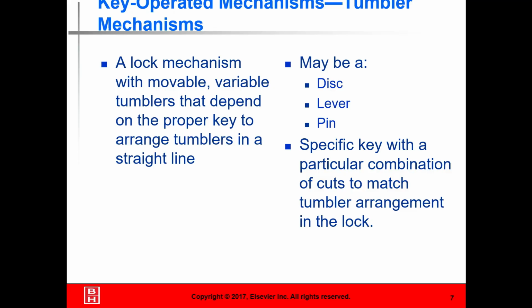So how does a tumbler mechanism work? This is the inside. Almost every lock has some type of tumbler in it. You line it up, and it allows you to open it. If the tumblers aren't lined up, then we can't open it. It may have a disc, lever, or pin; we'll talk about the differences of those in a little bit. The key has depth and ridges on it, and the idea is to make sure all the tumblers are lined up before they turn.